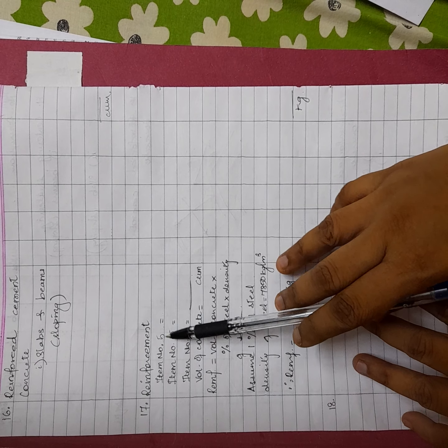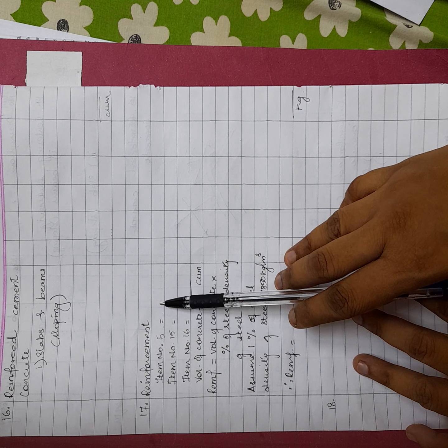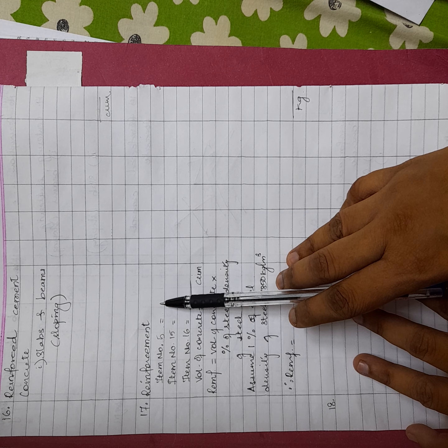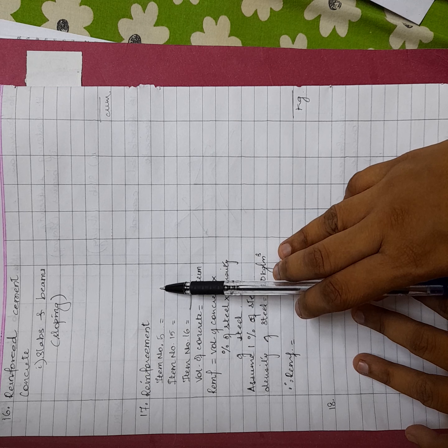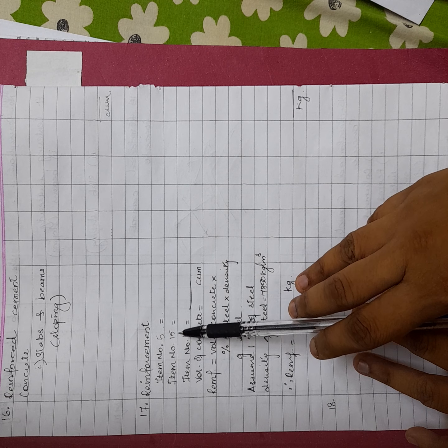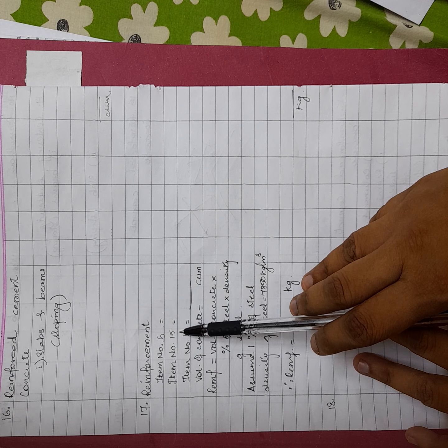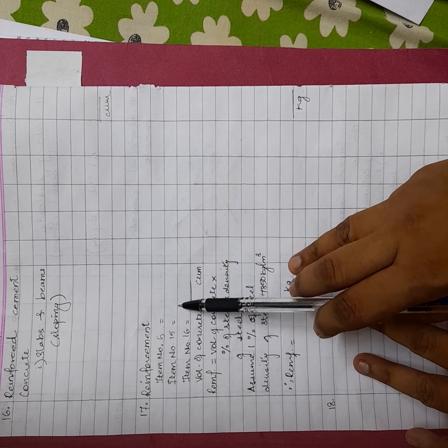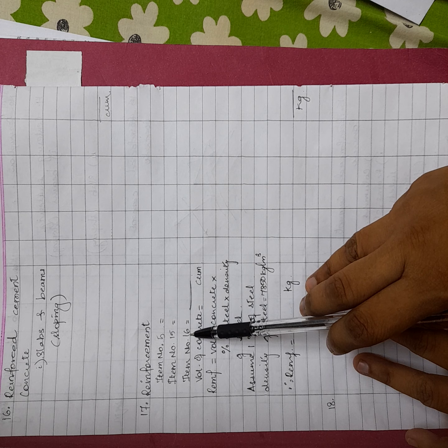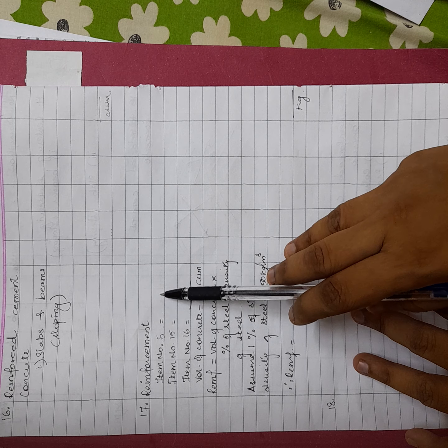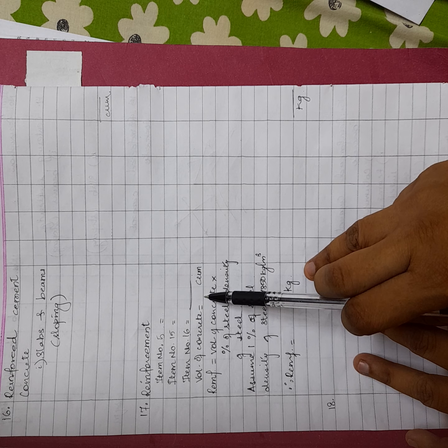Item number 5 will give you the volume of concrete occupied by footing, and also the volume of concrete occupied by columns till plinth level. Whatever you get in the quantity column, you have to write here, the final value. Similarly, from item number 15, that is for flat slab, columns, flat beams, lintels, you have to get the final value in the total quantity column and enter here. Similarly, item number 16, that is slabs and beams for sloping area, that quantity you have to write here. Add all these three and you'll get the volume of concrete.